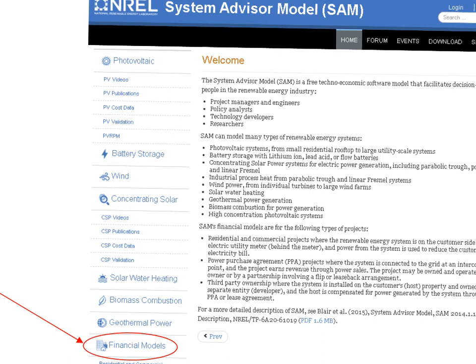So these are huge facilities. Basically they come in containerized trucks. If you were to look at them, it's an interesting look, but it's basically a shipping container that you'd see on a boat. They're pretty standardized, and you have doors that you can swing open, and then you can access the battery racks. Literally they just have stacks of batteries on top of each other, and those are the cells. You need lots of cooling, because if it gets hot inside there, the batteries will degrade very quickly. So they have big cooling units. And at one end of the container structure is a controller to help manage, control and monitor the batteries to figure out what's going on.